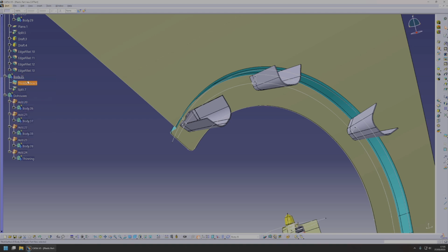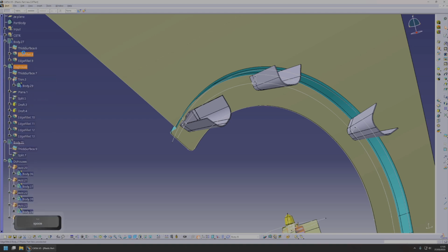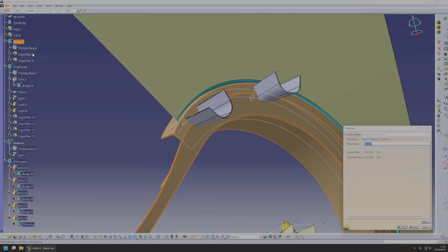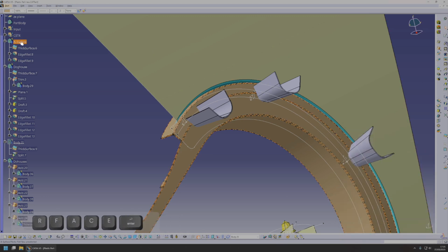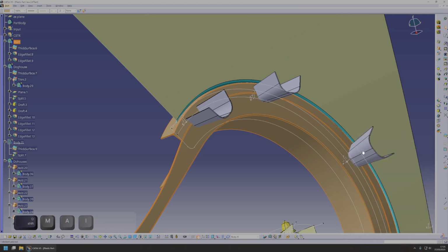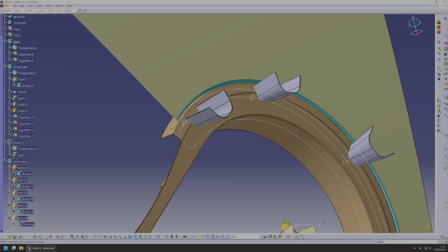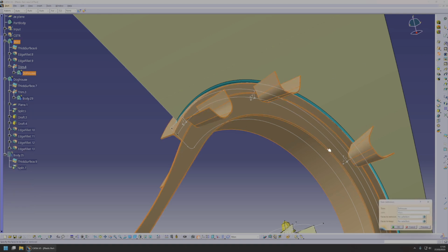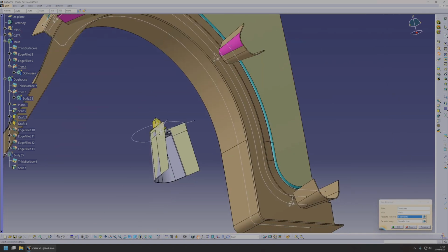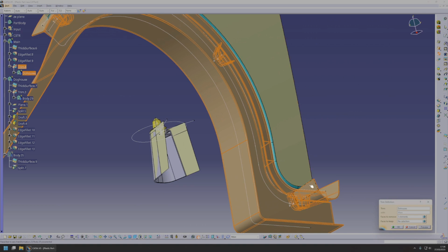And now you go to this one. No, sorry. This one is the main body. So this, you put here a surface, and then under the, no, it's not a surface, it's, call it main. And here you do a union trim this time. And you select these ones, and then faces to remove. I don't know if it's necessary to remove all of them. Let's see. Yeah, it's necessary to select at least one face from each body.